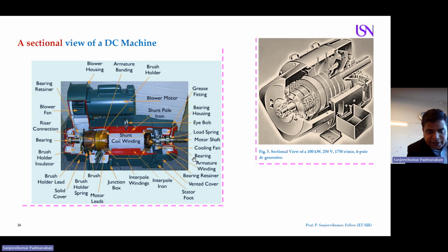Then we are using bearings. You have bearings here on the external connection. Do you know the meaning of bearings? Like the bicycles you are using, the same bearings will be put here. Ball bearings will be used to avoid friction between your shaft and the external load, for smooth running. Then we use grease inside.